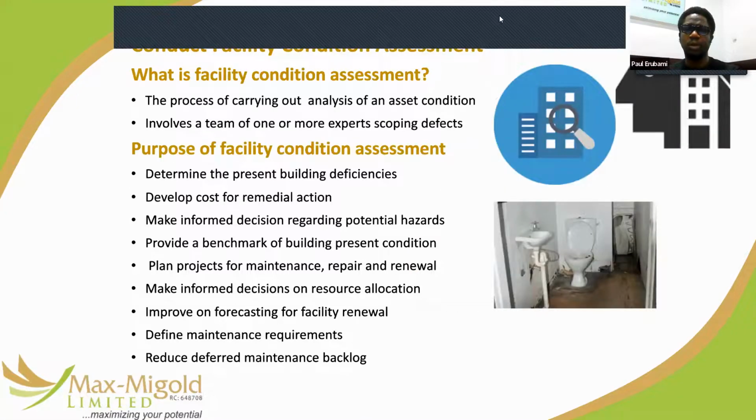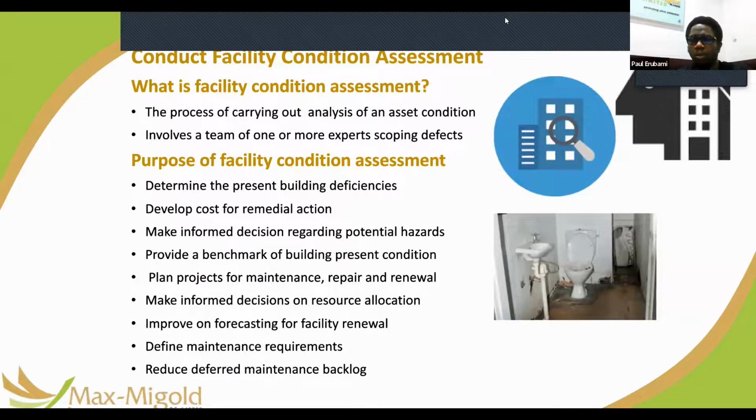And we've talked about knowing the condition of your assets before you define your maintenance program. In fact, perform your condition assessments, determine the condition of the assets, and create all of the repair work that needs to be done to bring the asset up to a certain standard that aligns with the corporate objectives. Now, those are what we call remedial works. They can be prioritized according to criticality, safety, and relevance to the organization.